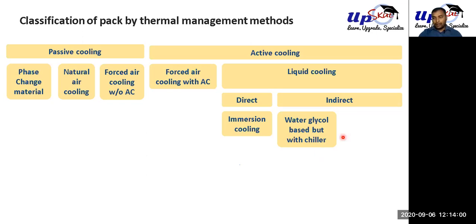Okay. A chiller is a component that actually connects the air conditioning system with a water based cooling system. Suppose you have cooled down the water using the radiator. Radiator can never make the water cooler than the environment, right? But the chiller can. Inside the chiller, from one side, our refrigerant enters, which is at very low temperature. On the other side, our water enters. And when they pass each other inside the heat exchanger, they don't actually mix. So the water becomes very cold.